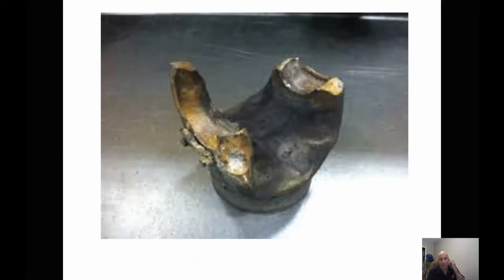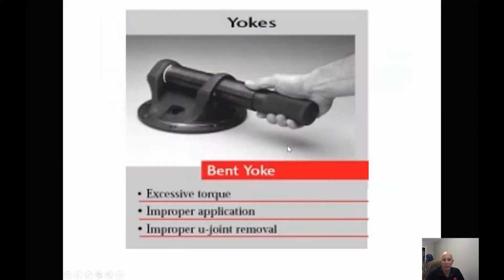The other problem we might see is having a U-joint that's being ripped apart. It's too much load on the U-joint and it just comes apart. Now, we talked earlier about the caps, making sure that the caps slide in. So there is another tool that we can use that we slide in through one and to the other, and if it slides through both of them, the yoke isn't spread, because if we take the yoke and we spread it a bit, the angle will change and this bar will not fit into the two yokes, so we know that we've got a bad yoke. If it fits in there, it's not an issue.